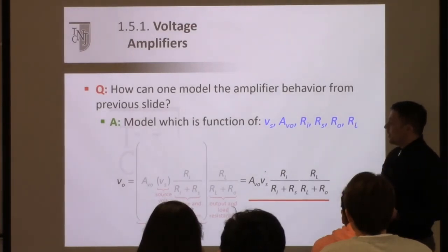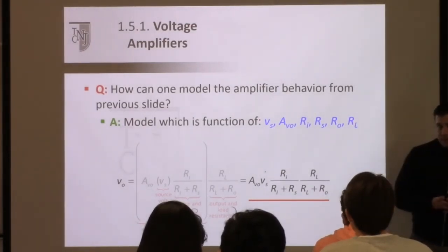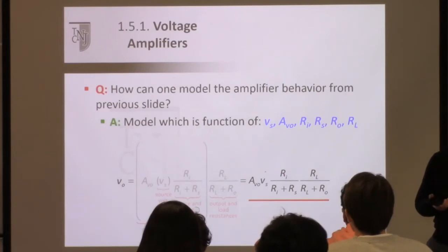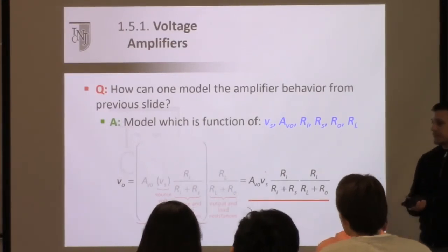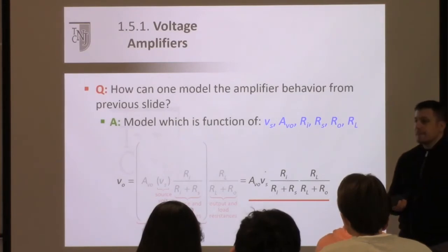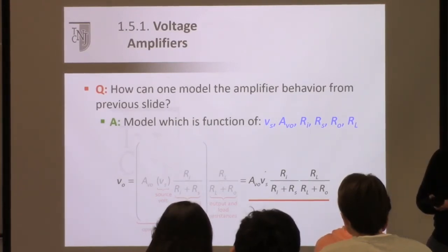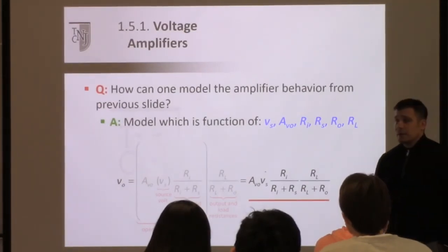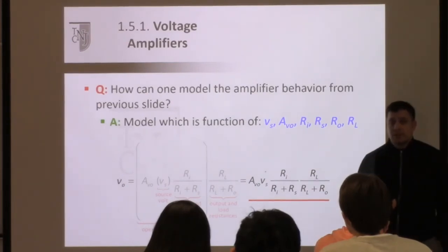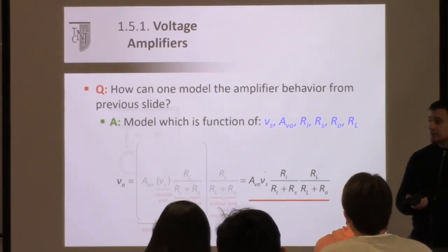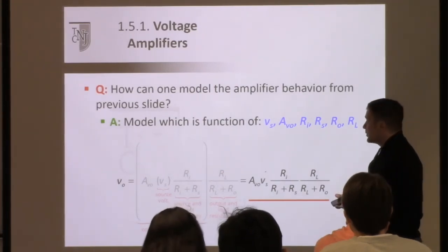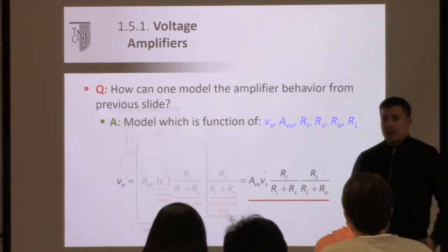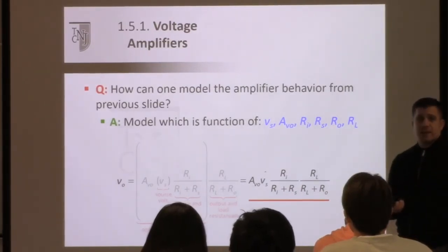And so it has a lot of different parameters. Is this normally the way we want our amplifier to work? What's the problem? So we want our gain to always be the same. We don't want our gain to be dependent on the load. Okay? The load can, especially if you're working with certain types of devices, fluctuate with the signal. We also don't want it to be dependent on the type of source that we're using. Right? That would be like having our iPhone do all kinds of crazy stuff depending on what type of